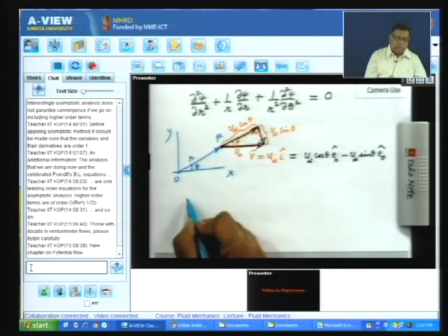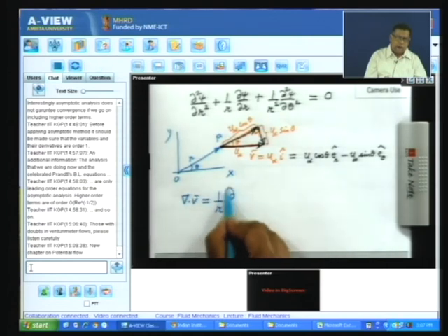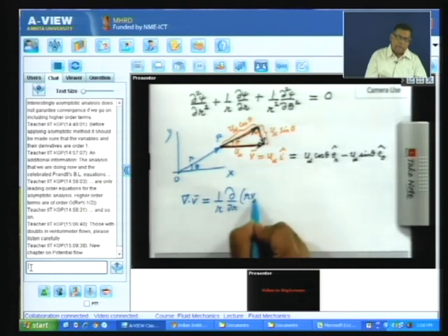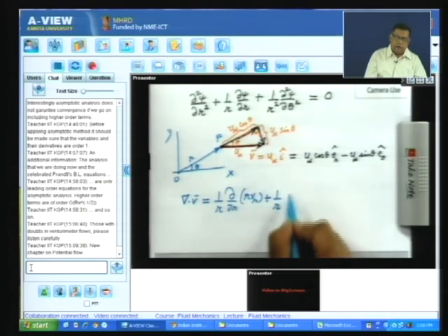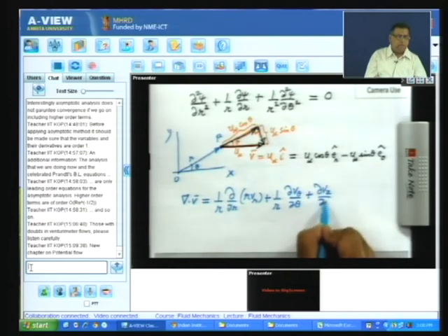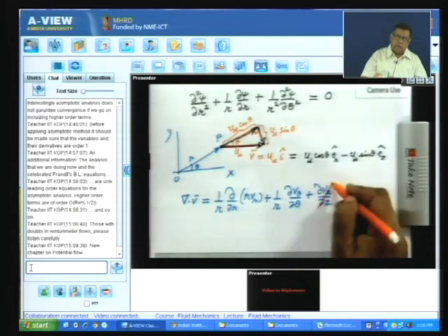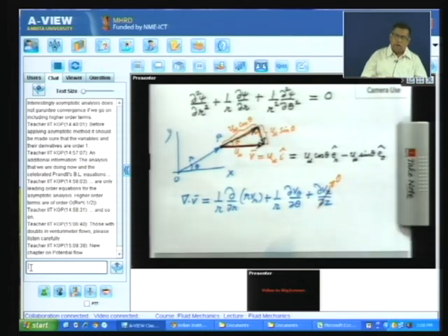Now, we will look at the expression for divergence of V in cylindrical coordinates. So, that is 1 by r del del r of r V r plus 1 by r del V theta del theta plus del V z del z. Now, for us the z component is 0, so this is not there. Conservation of mass tells you that this is equal to 0. You have the 1 by r factor here and here, so that can be dropped and we can write it as del del r of r V r plus del V theta del theta is 0.